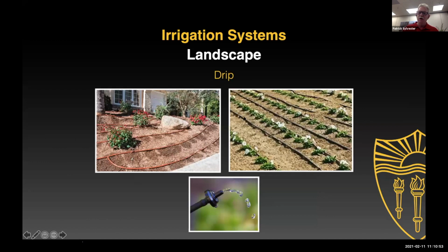Same thing here, if water pools around one of these areas, debris gets in there or backsiphonage occurs, whatever's near these openings can be siphoned in. Again, that's going to be a concern. I would certainly look at that as a health hazard because whatever could be on the surrounding ground could be anything.